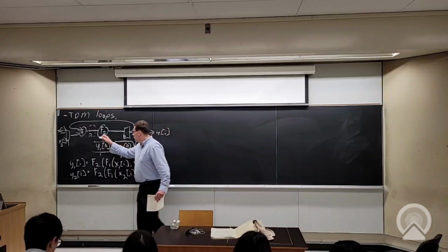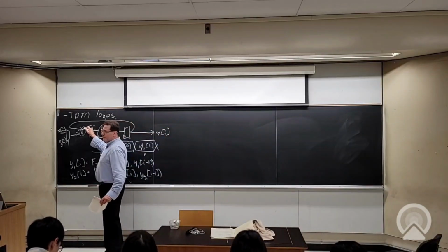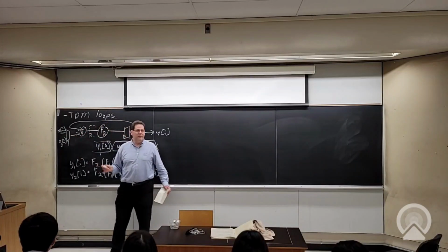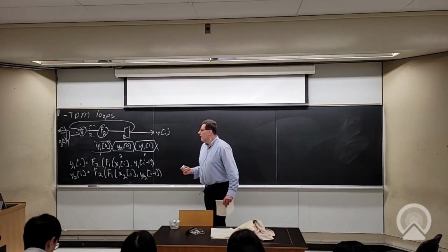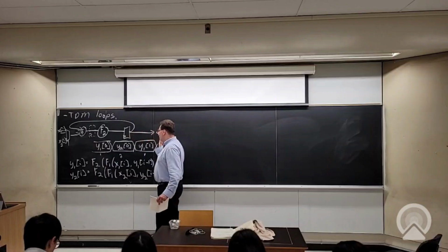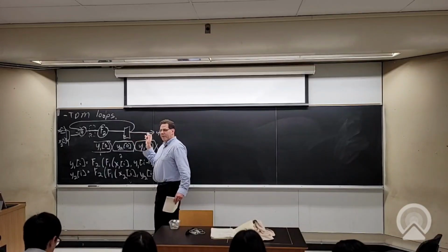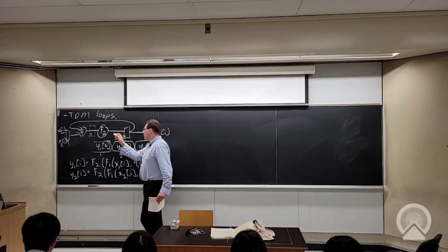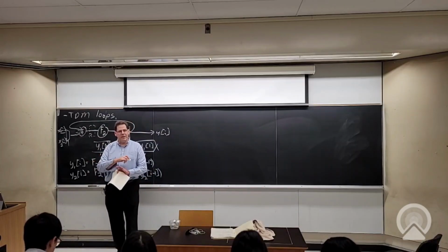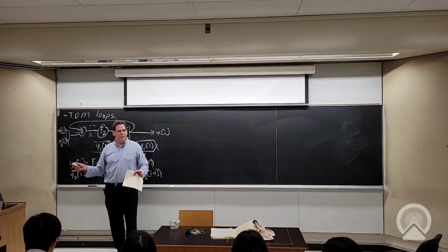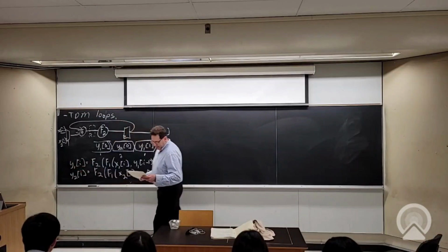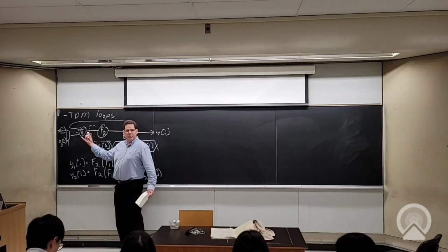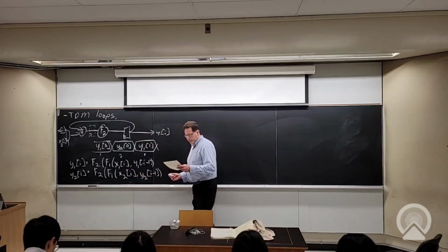If this was a loop with a lot of logic on it, putting a pipeline register in will make it run nearly twice as fast. So this was pretty efficient. I put in 2 streams, and I only get a value for each stream every second clock cycle: a value for stream 1, and then also a value for stream 2. But I can clock it about twice as fast. So each stream goes through about the same speed as it used to, but now I get 2 of them. And I couldn't do this with just straightforward pipelining, because I would have changed the functionality.